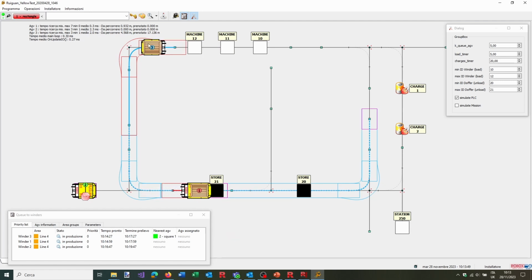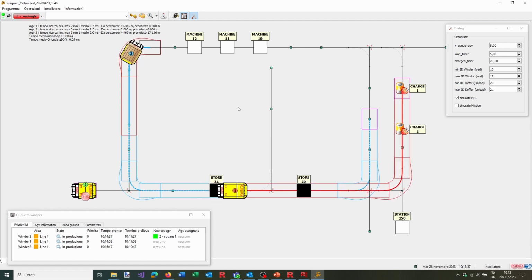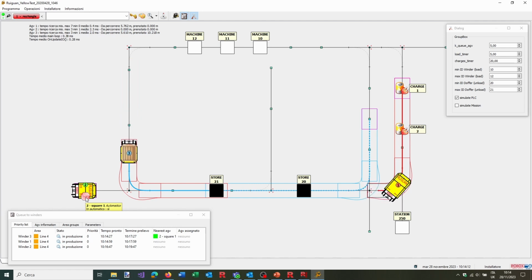If the distance is longer, you know that the AGV will never stop, and normally this can be a help because the AGV will move only when a bigger part of the path is free. But for this reason, other AGVs will not be allowed to cross, and so if you have a system with more AGVs, you may have more problems and less efficiency because more AGVs will just wait even if the other AGV reserving the path is still so far and they have the time to cross.